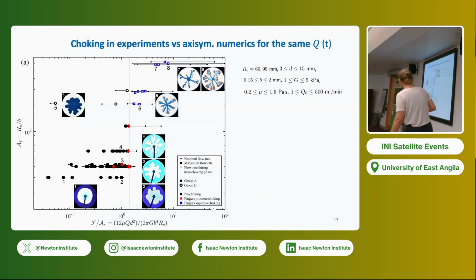In this direction, we're changing how deep the cell is, so how narrow the gap is initially. In this direction, we're changing how quickly we're injecting liquid. So if you look at the bottom figures, for example, we go from having an approximately axisymmetric interface to having a fingered interface. What's important to notice in this direction is that as we change the parameters, we go from having wide fingers to having much narrower fingers. And that's something you would expect for Saffman-Taylor instability.